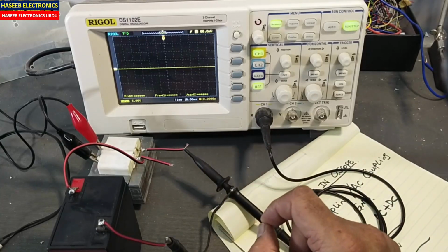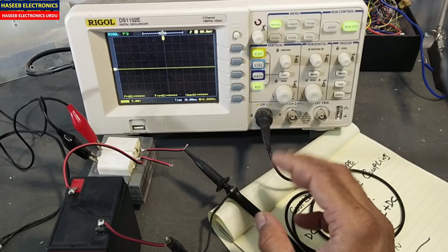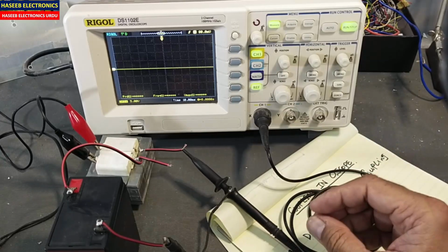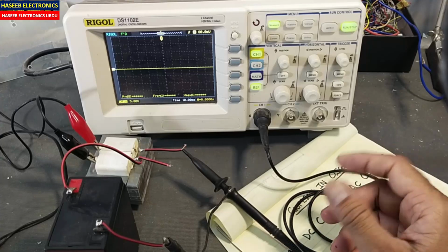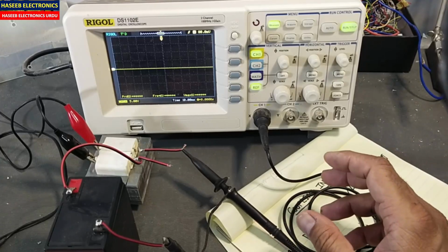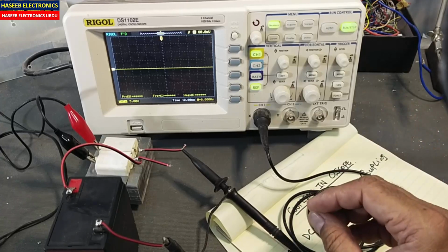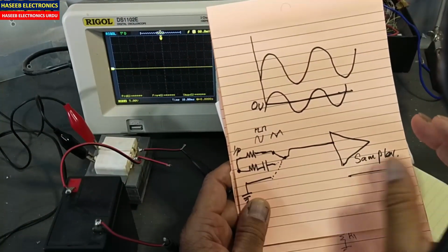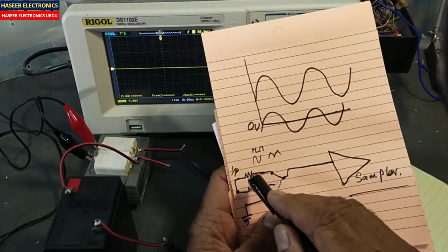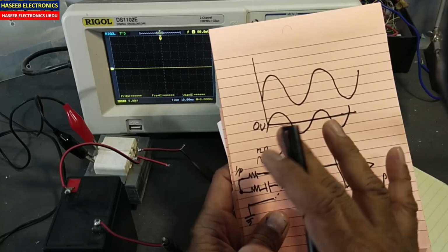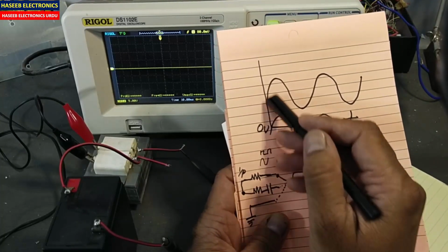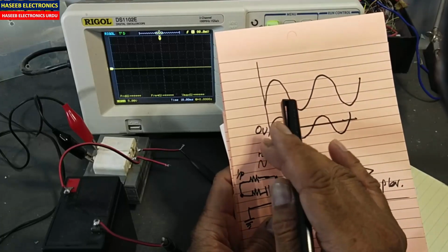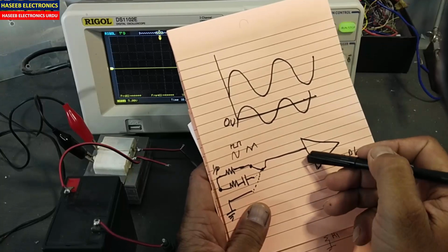The same technique will be used in analog oscilloscope, in cathode ray oscilloscope, in DSO, DPO, that is digital phosphor oscilloscope, MDO, mixed domain oscilloscope, MSO, mixed signal oscilloscope, and digital sampling oscilloscopes or waveform recorders. The same configuration, the same function, the coupling will be used in the measurement. When we select DC coupling, each type of signal, either positive or negative, either it has DC level, AC level, or distortion, whatsoever, it will pass to the sampler and the sampler will show it on the display.